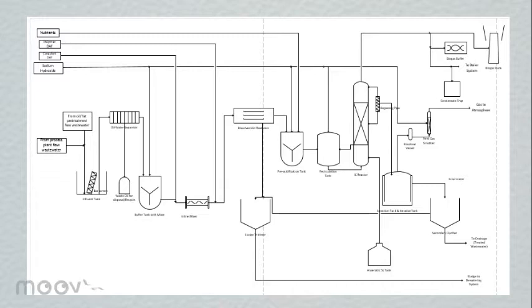Sludge will be collected from the secondary clarifier and the DAF. The sludge discharged from the secondary clarifier and the DAF has low dry matter content. In order to increase the dry matter content, the sludge has to be further dewatered by mechanical dewatering equipment.